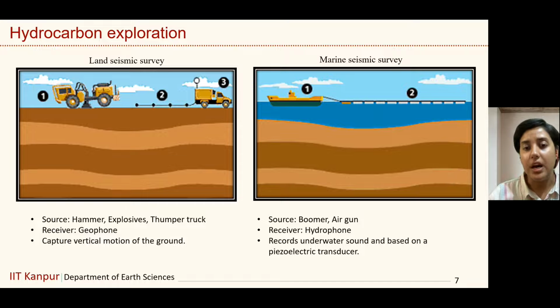And this hydrophone is based on the piezoelectric transducer, meaning that it converts the pressure wave that we receive at the geophone, or sorry, the hydrophone, into the electrical voltage, and that voltage can be mapped in the form of amplitude of the received seismic wave.